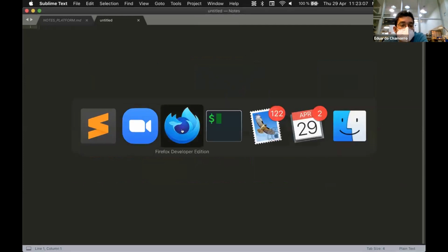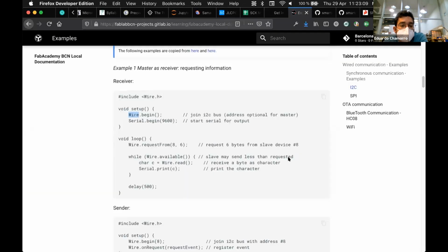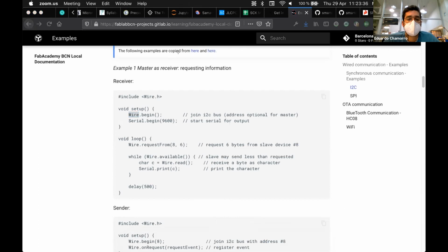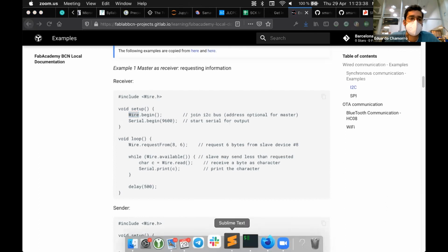So, things about I2C, some of which we discovered yesterday. ESP apparently doesn't like to be a slave. I don't know what the connotation of that means, but basically there are some issues there, and you, Adrian, were doing quite a good research on that yesterday. Now, going a little bit deeper into the things that we didn't talk about yesterday, besides addresses and this type of things, there is quite an important note on